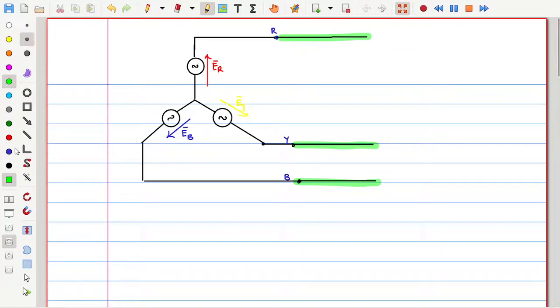Now, if we observe the voltage between R to Y, we call as line voltage as ERY. How do we get ERY is just simply write down the KVL we will get in this way. See, so start at the arrowhead of this ERY. So from here and reach to the other side through this path, like here Y phase, like we started at R phase line and we reached to the Y phase line.